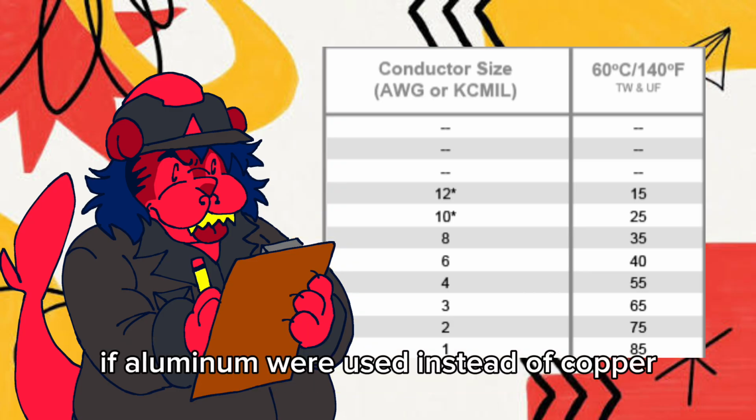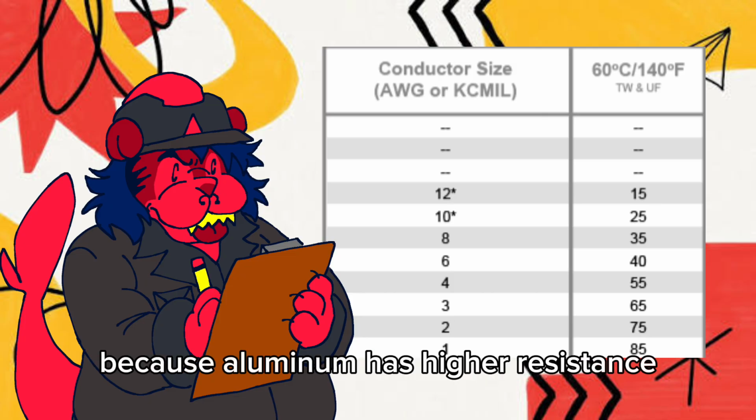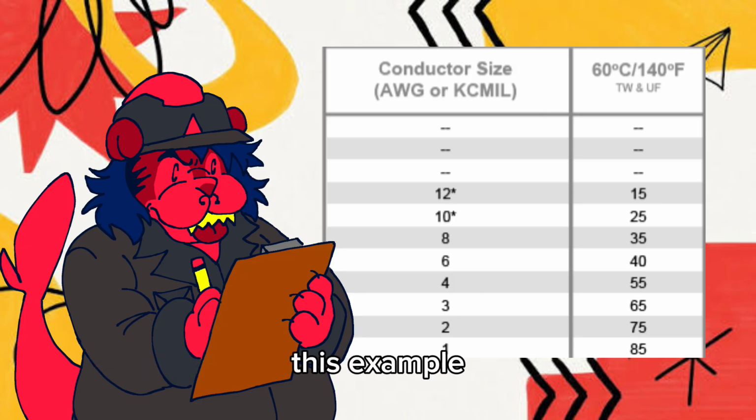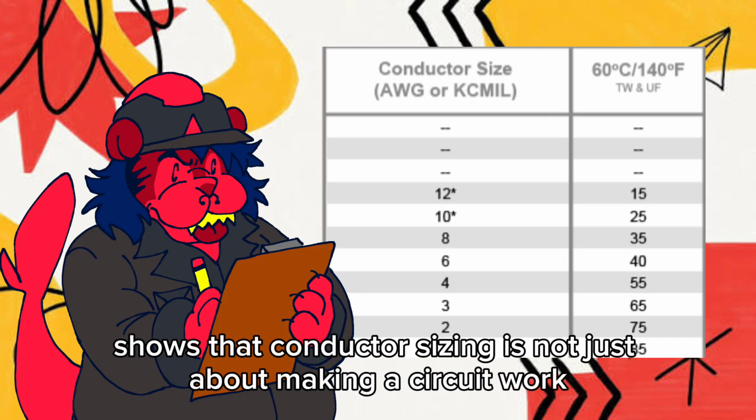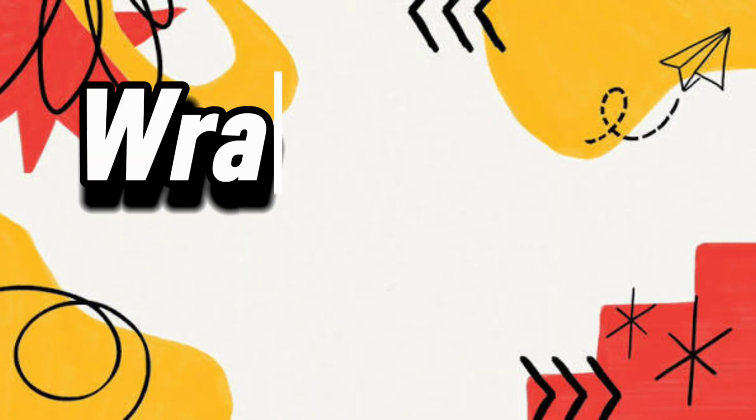If aluminum were used instead of copper, the wire size would need to be increased because aluminum has higher resistance. This example shows that conductor sizing is not just about making a circuit work. It's about selecting a wire that can carry current safely without excessive heat.